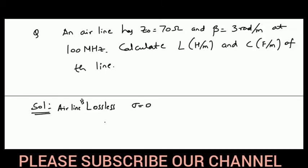For a lossless line, we know that R equal to G equal to 0, and its attenuation is 0. Now Z0 is given and beta is given to me. For a lossless line, beta is omega into under root LC. Since frequency is given, I can calculate the value of omega. So this is equation number 1.